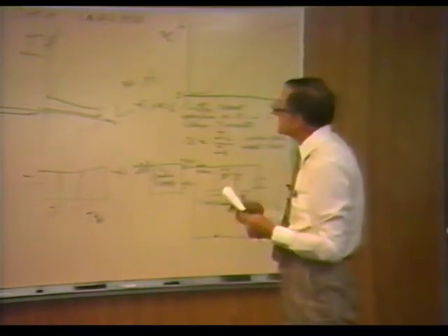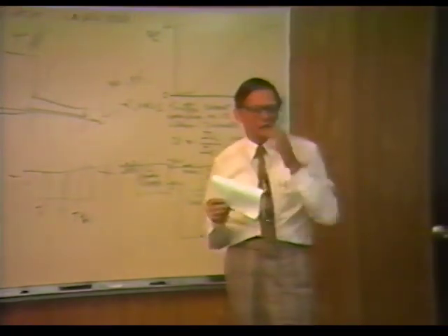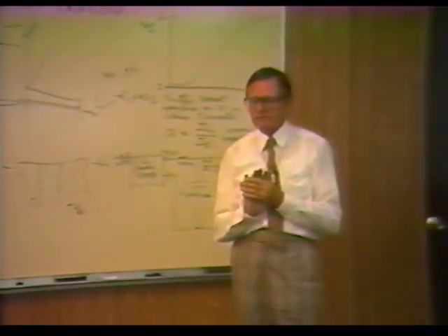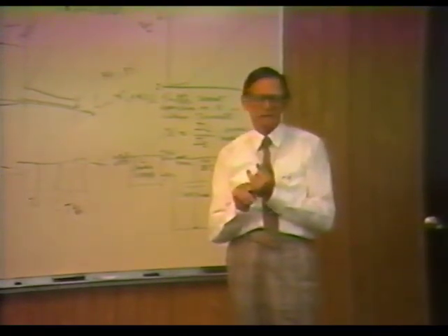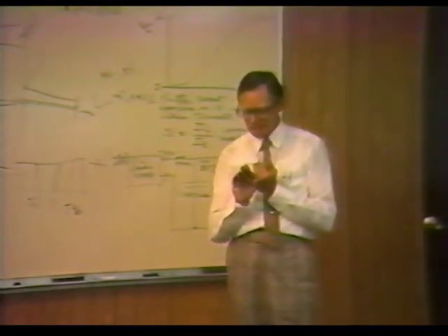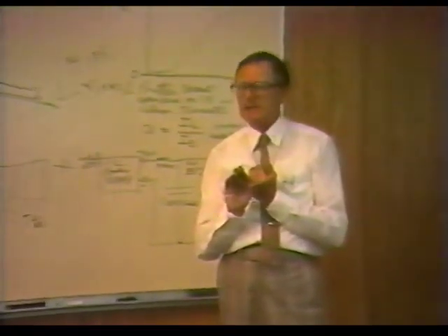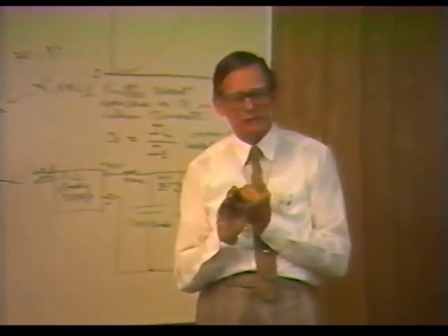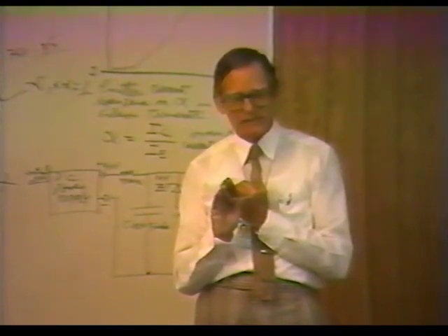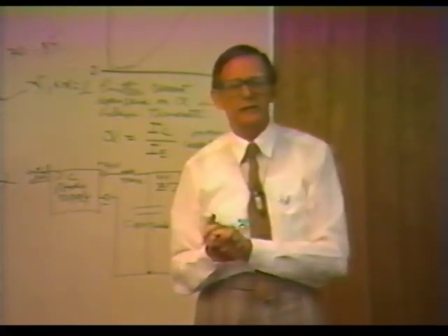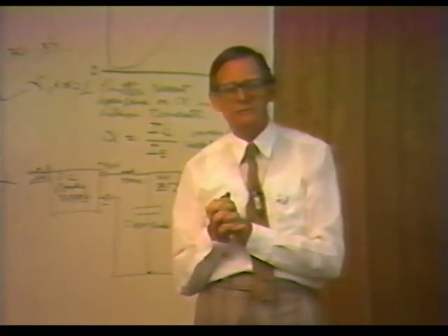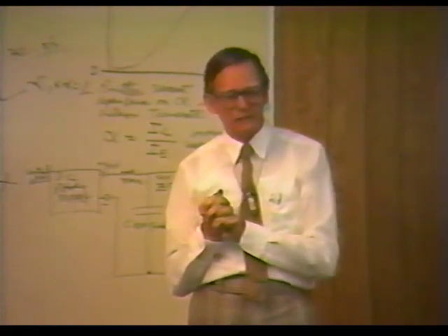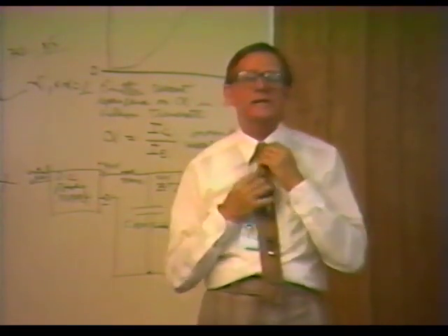I'll just end it by saying, do we have any questions at all about what happens on the SCR? In using them, remember that heat affects turn-on. That is temperature. The radiation affects turn-on. In a gamma radiation, they will turn on. So if you have voltages across the device and it's hit by gamma radiation, it will turn on. It will trigger it on. So in using the devices, you have to be careful to use them within the manufacturer's specifications. That's all I had to say about that.